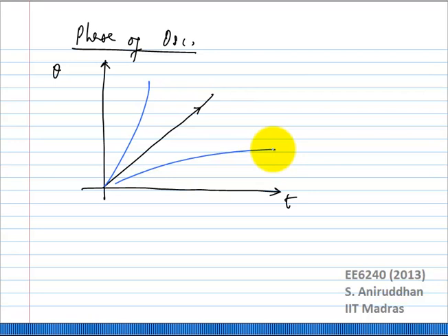If you look at the phase deviations caused by any of this noise, what do you expect these phase deviations to be in the long term? Correct. They should average to 0, or close to it. More or less, they shouldn't take you in any systematic direction, but they will operate on the phase of the oscillator. So what you really expect are neither of these. You actually expect maybe something like this, which may overall take you along the same path as an ideal oscillator, but there will be short-term deviations. Over the long term, it should stick to the same characteristic. That is what we know.